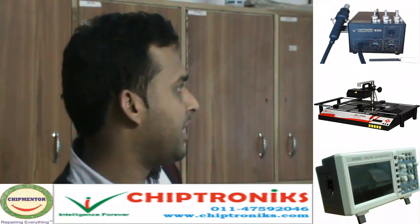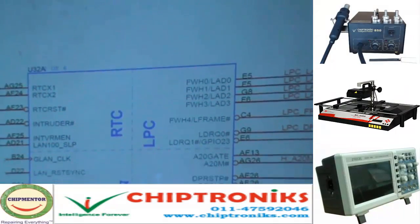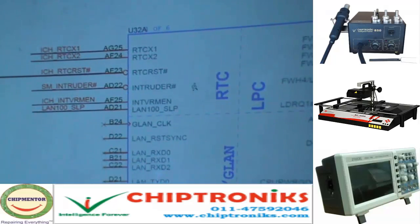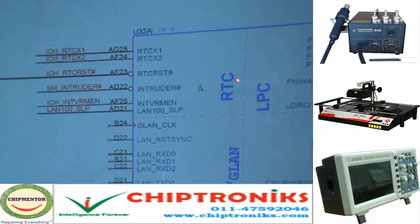Here, page number 19, U32A 1 of 6. This diagram is divided into 6 portions. Let's start from the RTC, real time clock. This is very important for feeding the real time clock present over here. The important thing is it's driven through ICH_RTC_X1 through a crystal.